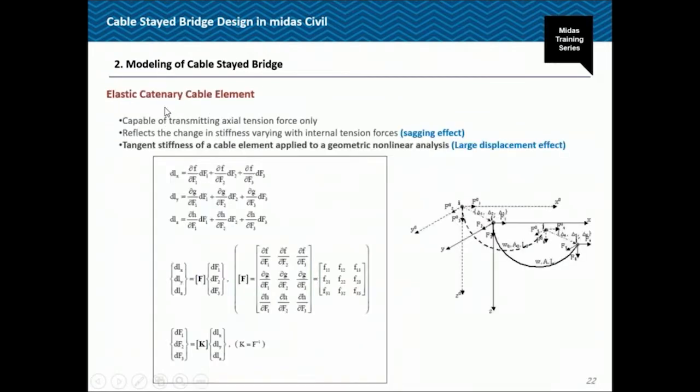Coming to exact catenary cable element, catenary element, that time when you're performing the large displacement analysis, the program converts the cable element to this catenary cable element, where the geometric stiffness would also be included to calculate the stiffness of the cable element.